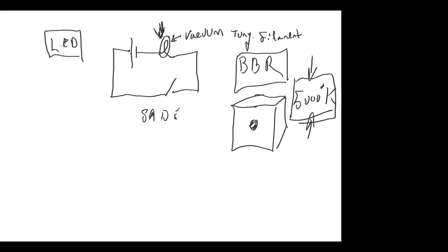Another way to do light, right? Because LEDs, they're not fluorescent bulbs, okay? And they're not incandescent bulbs. Instead, what they are using is electroluminescence. Electroluminescence is the result of recombination of electrons and holes across a barrier. So this is another way in which you can generate light. It's very efficient.